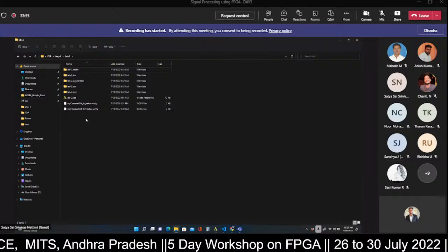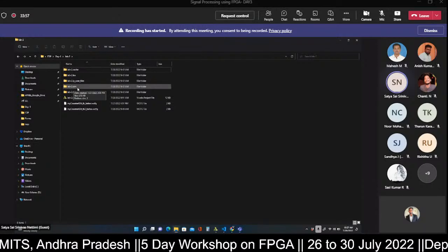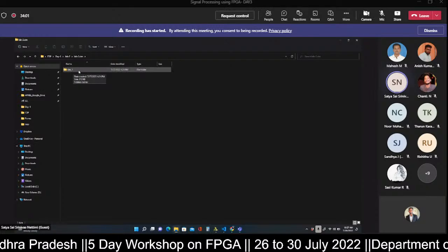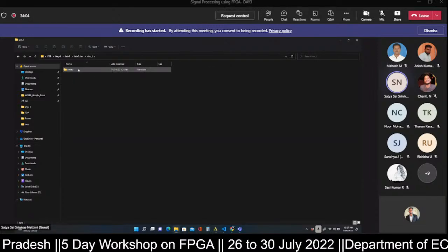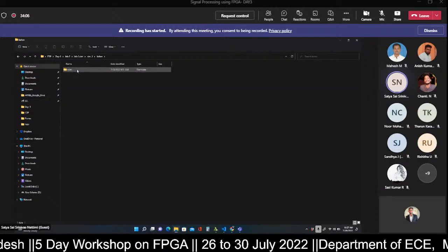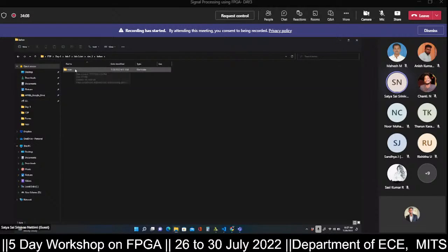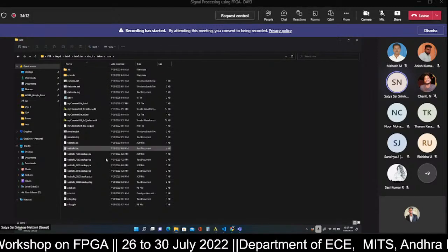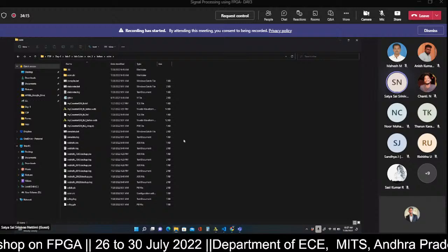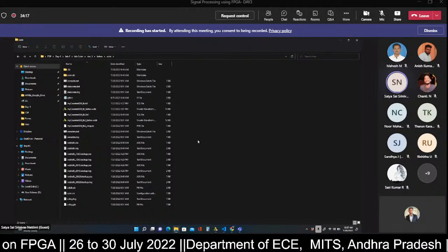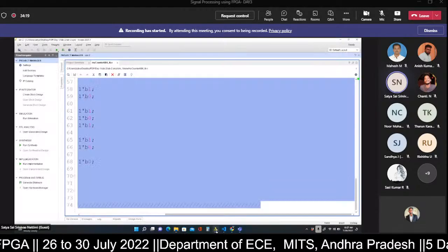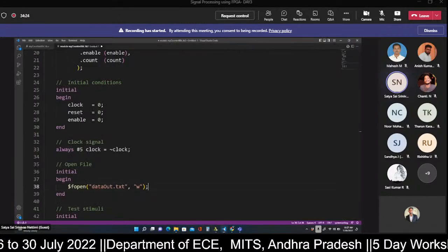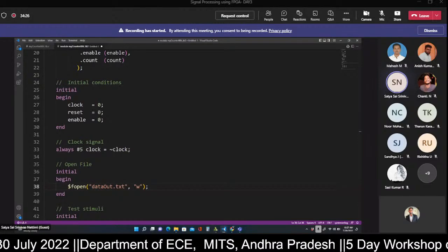There is a folder called lab-2.sim, under this a sim_1 folder, under this a behavioral folder, and under this an xsim folder. The file will be created by default in this location, and the lifetime of this file is dynamic in nature. It is not fixed, so whenever you relaunch the simulation the old file will be deleted.